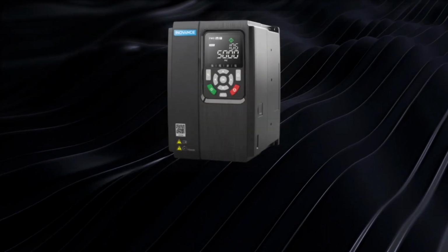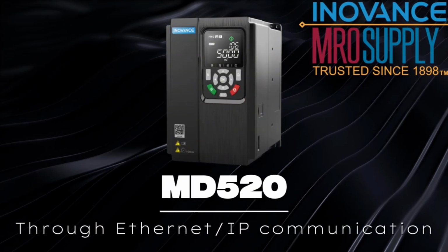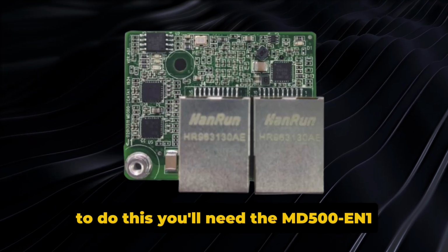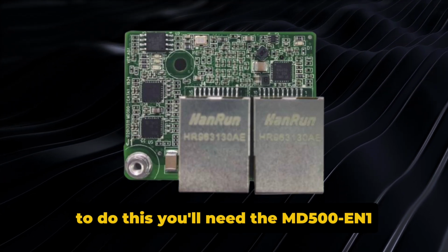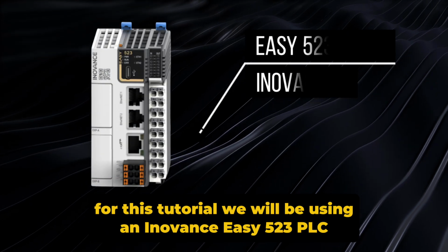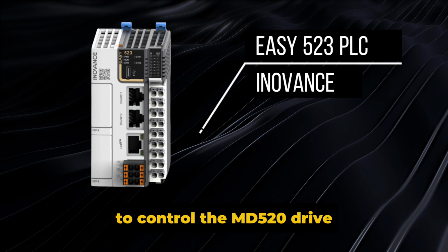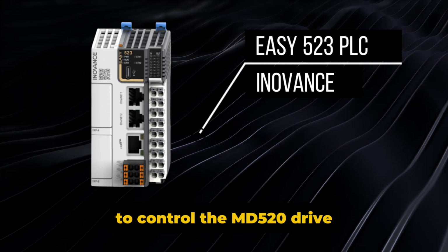In this video, we will be discussing how to control the MD520 through Ethernet IP communication. To do this, you'll need the MD500-EN1 communications expansion card. For this tutorial, we will be using an Inovance EZ523 PLC to control the MD520 drive.